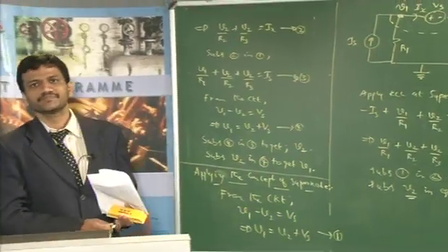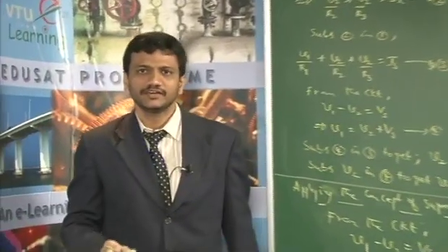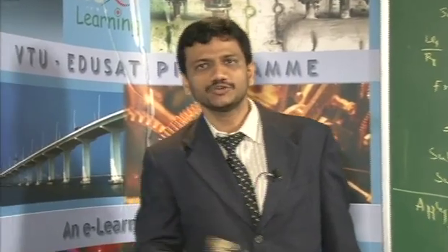So, definitely whenever a voltage source appears in common to two nodes in node analysis, applying the concept of super node greatly reduces the number of steps involved in obtaining the solution for that problem.